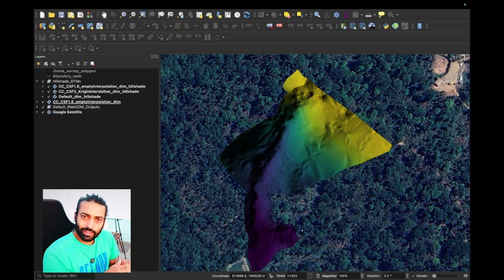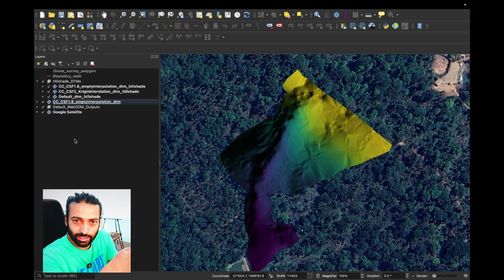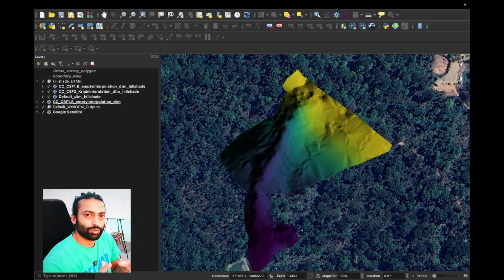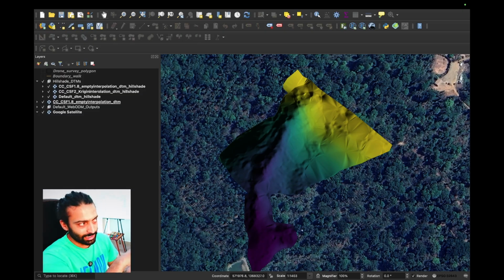Once we've arrived at our usable DTM, which is cleaned up, I've also gone ahead and cleaned up the project space. This means grouping the layers inside of QGIS and also deleting all of these several files which have been created in the process of iterating on the different point cloud processes and also the DTM imports. So it also goes to show that there is a little bit of iteration and an art and a science to actually cleaning up the digital terrain model from a point cloud from photogrammetry, and then you can arrive at something like this.